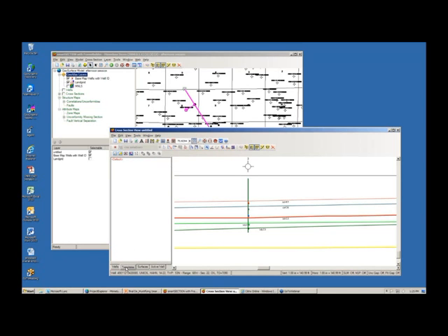Now, in the Templates tab, we will soon have what's called a cross-section template. This is equivalent to the X-section cross-section templates. Basically, it contains the look and feel of the cross-section, such as the distance between the wells, whether the wells are displayed as straight or deviated wells, well-related header data, what color your surface is going to be. All these things can be basically frozen in time and used over and over again by just coming into the Templates tab and selecting them.